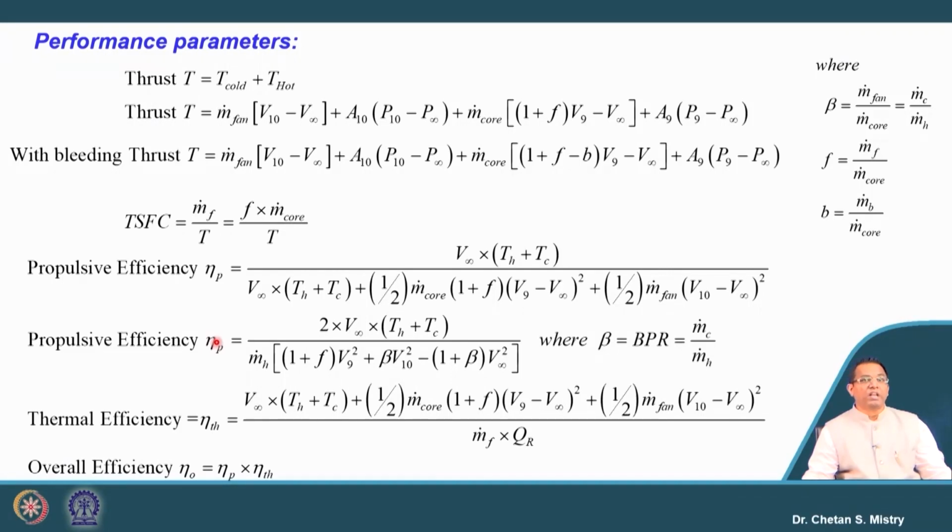Okay. So, once we calculate our propulsive efficiency and thermal efficiency, we can do our calculation for the overall efficiency. Now, here you may get the question saying, sir, for turbofan engine we are discussing the bleed. Do we have this bleed for turbojet engine also? The answer is yes. There are turbojet engines where the air is bled for special requirements.